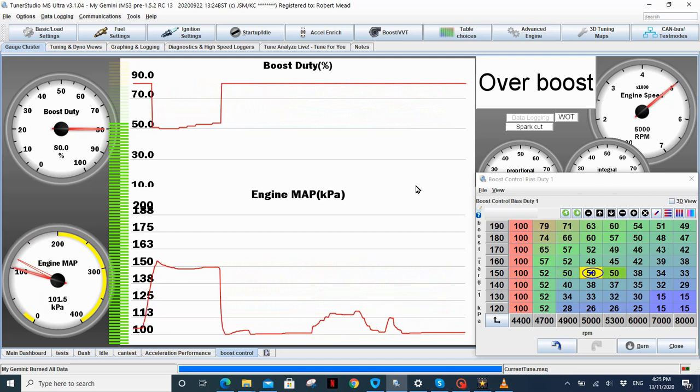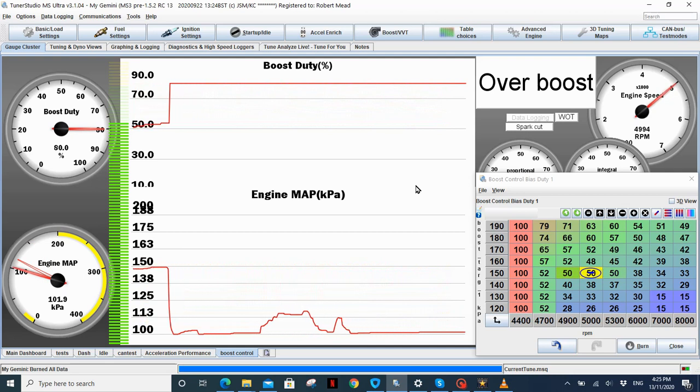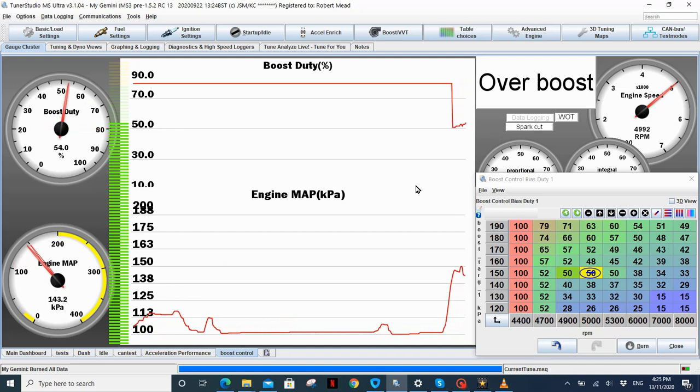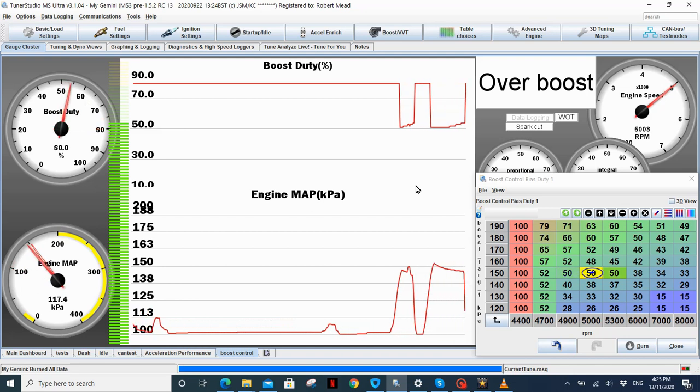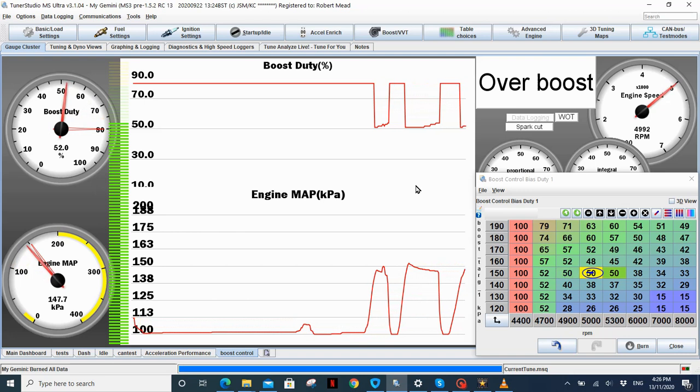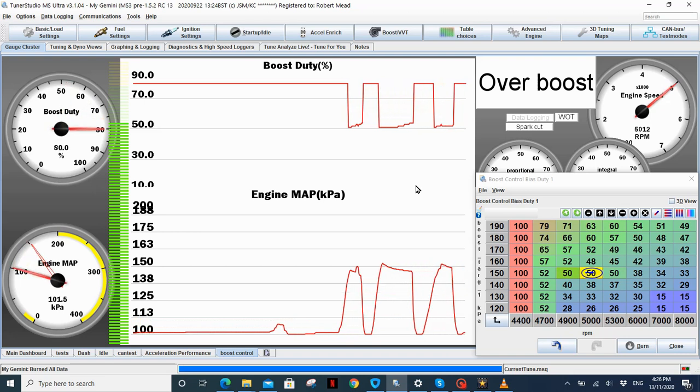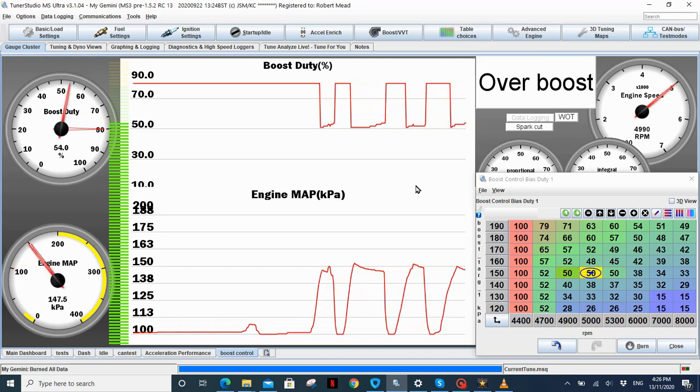Whereas when it only starts to make a difference when it's 15 kPa, the error signal is nowhere near as big, and it's not going to shoot up at that massive rate. It's a little bit of an error, and it'll change a little bit, but you can see there, even coming up boost slowly, it's going to hit pretty close to your target.